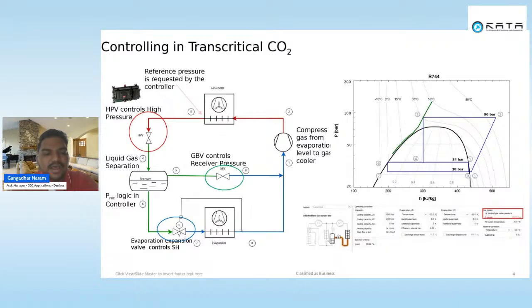The pressure drop from 6 to 7 through the expansion valve, you can see here on the right-hand side, and the pressure drop from 5 to 9, you can also see here on the right-hand side. The gas coming out of the flash gas bypass valve and the gas coming from the evaporator outlet will mix and come in as the compressor suction. That is point 1 in the pressure enthalpy chart. So this is a basic cycle. We call this a gas bypass cycle.